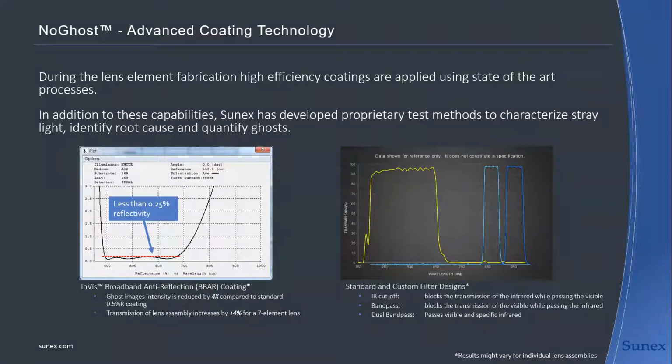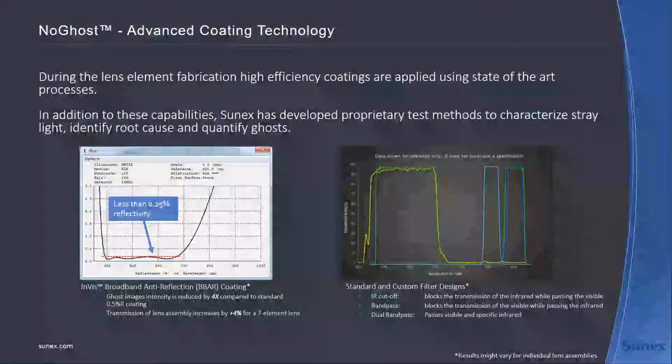In automotive, quite often we see driver monitoring applications centered around 850 and 940 nanometer. And then we have the applications which touch a little bit of hyperspectral. It's not going through the entire band continuously, but you have a dual bandpass situation where you want to have nice lens performance in the visible space during the daylight, but then you want to still continue monitoring your driver during the nighttime, right?